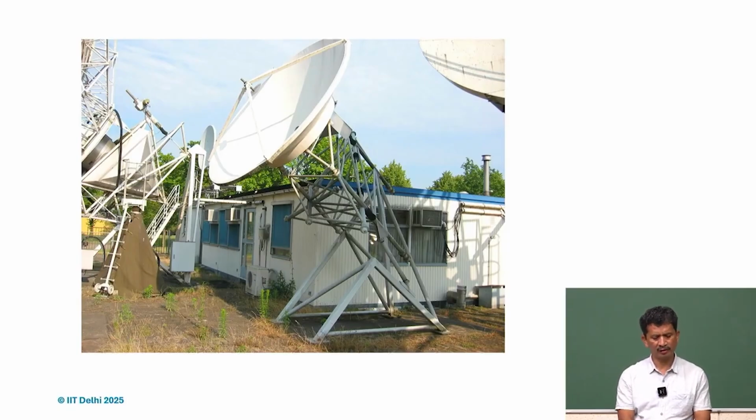I have seen it while doing my PhD, and there were smaller models also placed in the lecture hall there. So yes, even with the trusses and everything, a huge structure, it doesn't mean that you cannot use these flexures. The dimensions of this flexure do not necessarily have to be in microns or millimeters, but can be bigger, depending on the scale and the load capacity.